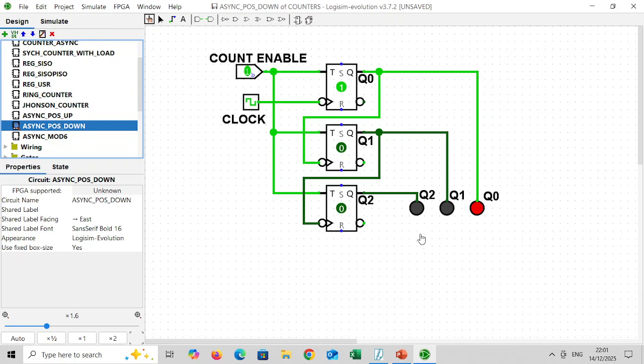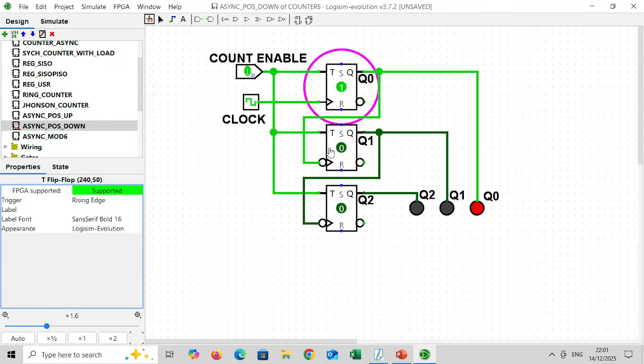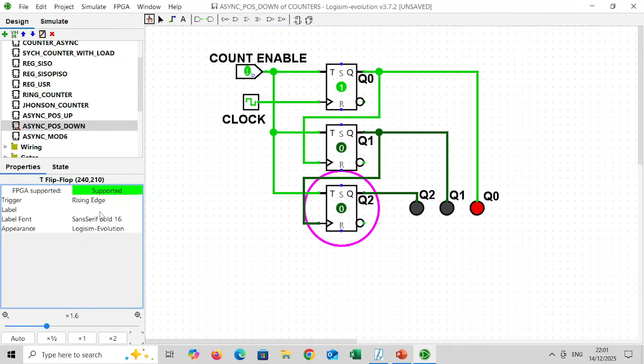So 3 is correct, so that we have used the 3 flip-flops. All are used as edge triggered positive flip-flops. So I'll configure them as edge triggered. Instead of falling edge, we'll take the first case as positive edge triggered flip-flops. Now, what is the way the flip-flops are connected one to another?